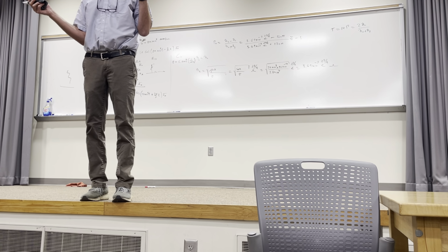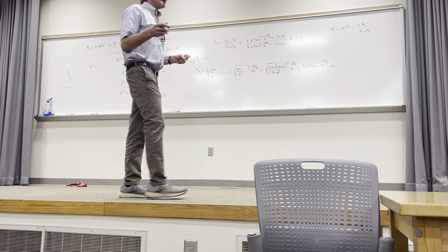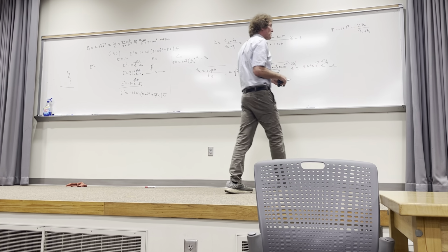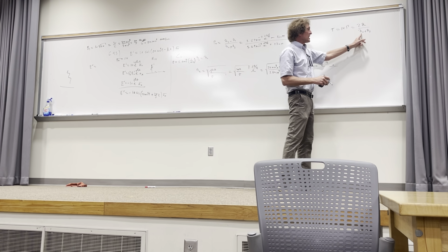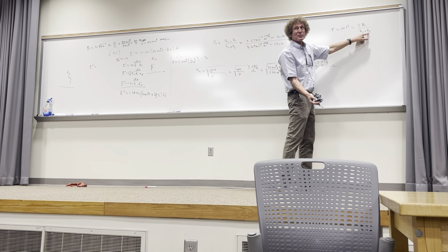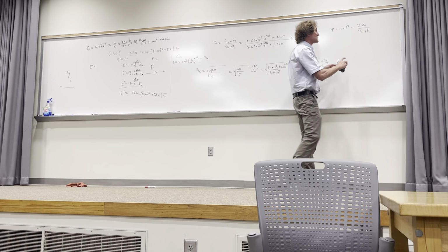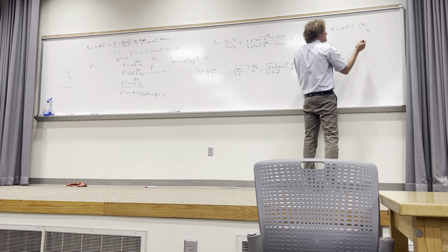That's always it. Now, here's how that approximation works. When eta 2 is so much smaller, take a look at this and make sure you see it. You see how you have eta 2, super small, 10 to the minus 3 kind of stuff, plus something that's about 377. So what we do is just get rid of that. And we say the transmission coefficient is about that.